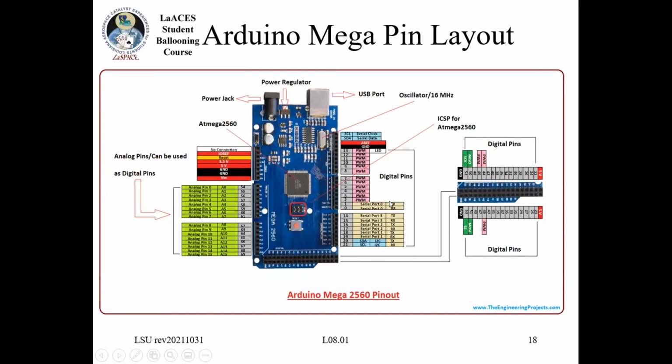After you did that first activity, you were actually using serial 0, which comes out the USB as well. If you were to connect to those pins, you would also have seen the UART communications that you were doing last time. And then there are 3 other serial ports, so 1, 2, and 3.